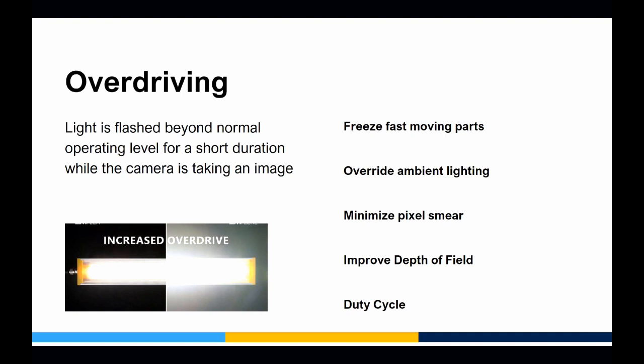about overdriving. And I will say that, if you're using a CCS light with a CCS controller or a Gardasoft controller, you don't have to worry about overpowering the light. Both of those controllers have built-in safety features to make sure that as long as you're putting in the rating of the light correctly, you're not going to overpower it. Essentially, the controller won't even let you. So it's important to factor in and know your duty cycle, but it's not critical if you get it wrong on accident when setting up your controller.